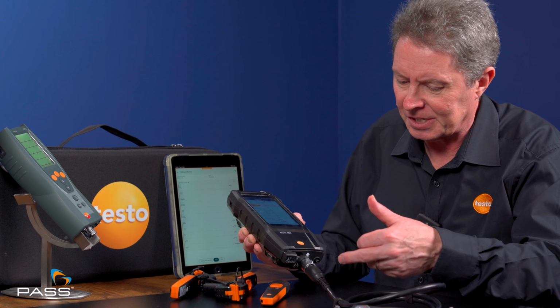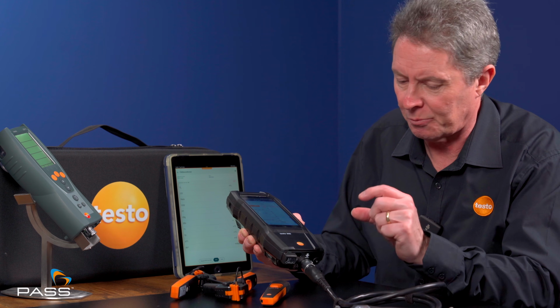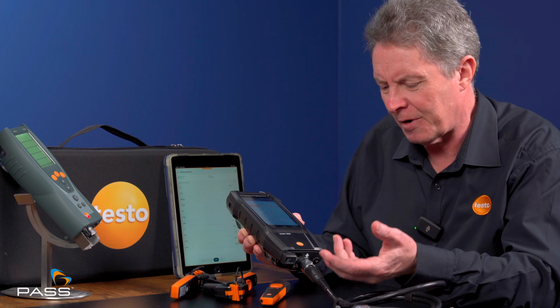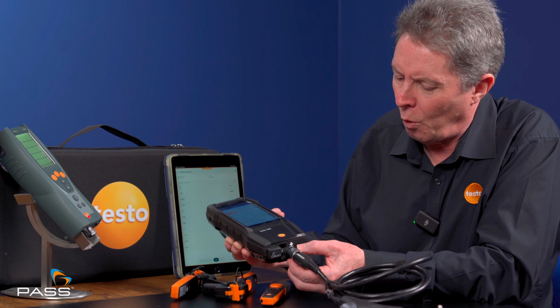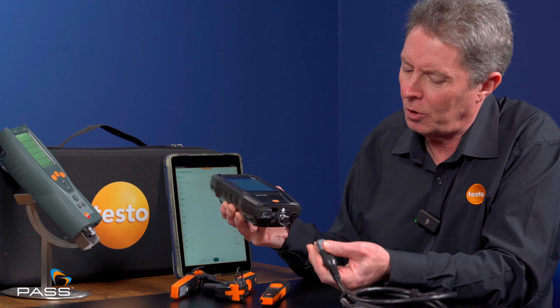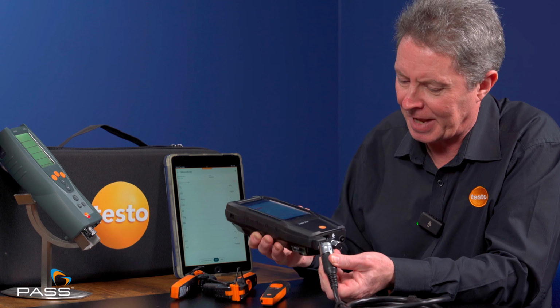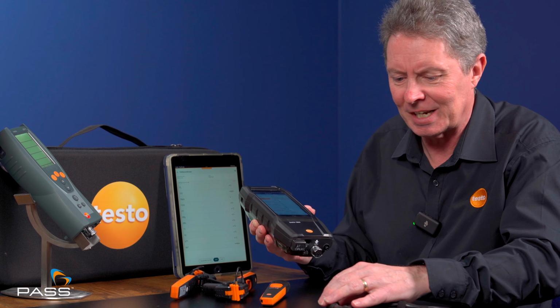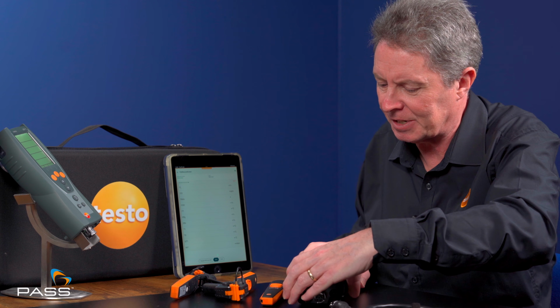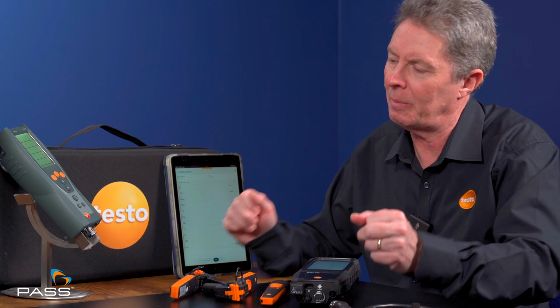A lot of other analyzers bring that down on a secondary connection, which is a little plug that plugs in, very prone to breakage. It can be a little bit flimsy. We've got all that integrated into a single locking connector. So that one connector brings down the gas pathway and your thermocouple. We believe it's little details like that that really set out our design heritage and thought about the reliability of the Flue Gas Analyser.